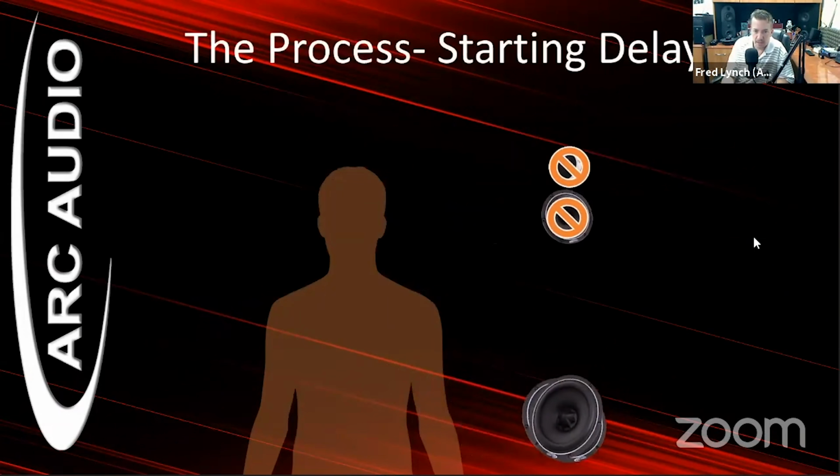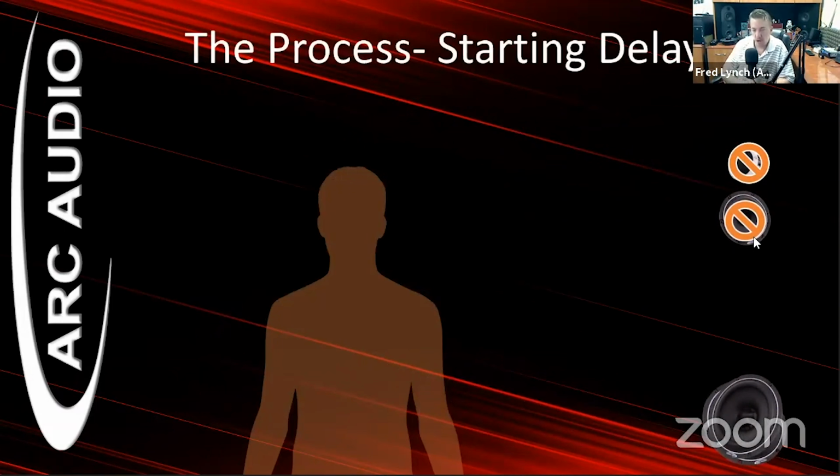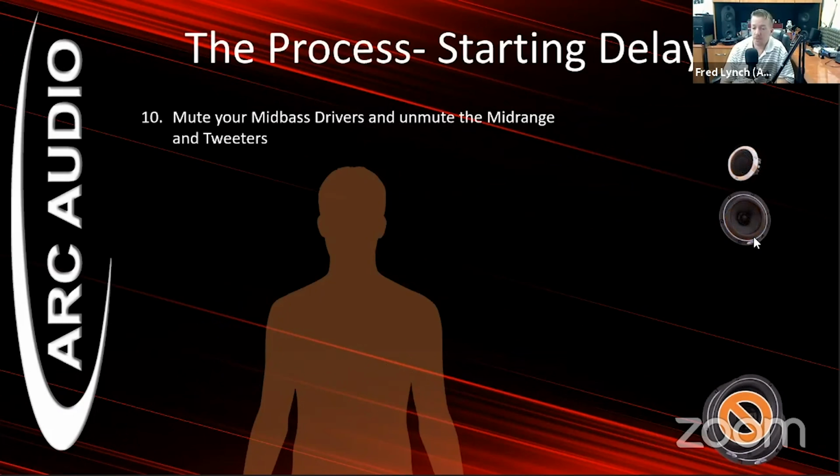Now we've got this, but the problem here is, if you look, all we've done is bring left and right together in center to create an arrival time at your ears at the same point between left and right. But in a lot of cases, we still have a very tall stage. It still sounds like your tweeters and mids are coming from up on top of the dash, and then you have the mid-bass drivers coming from the floor or the bottom of the doors. So we have to get these buckled up now.